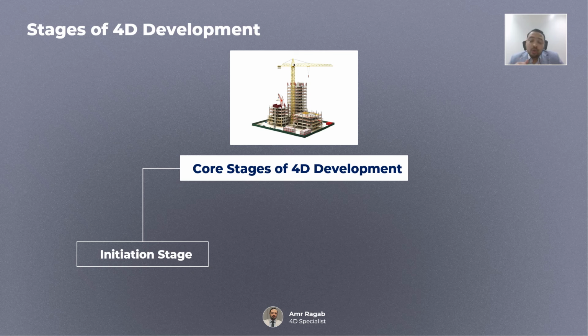The second point: you also need to review your baseline schedule and check the work breakdown structure. The problem I faced in the baseline is that I can't find the right task for a 3D element, so I can't assign it. There are missing tasks. So you will tell the planning team to add these tasks and develop the baseline and increase the WBS detail to be constructible. This is all about presentation and consistency.